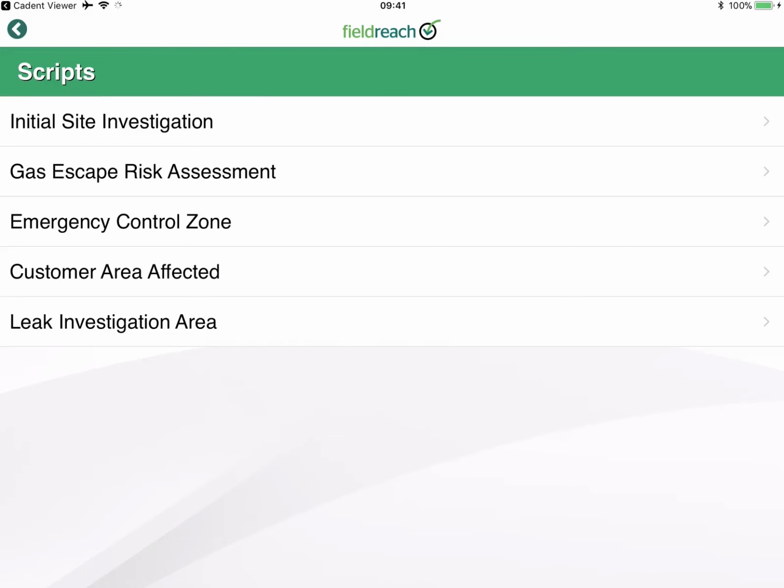So in summary, what I've shown you is how field workers can view their work orders on the device and then can view the location of that work order on their network maps by seamlessly switching to map view from task or work order view. And also how the user can select and open that work order form seamlessly from a map view to revert back to a form or a list view to complete their work. I then showed you how, again, the user can switch out of the form view and use the map to capture XY information, polygon, polyline, point, geospatial data. Maybe it's linear asset information as well, and that can seamlessly populate the relevant forms within tasks or work orders.